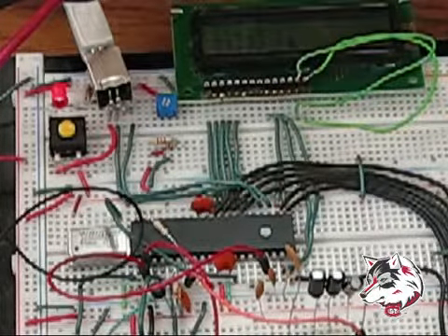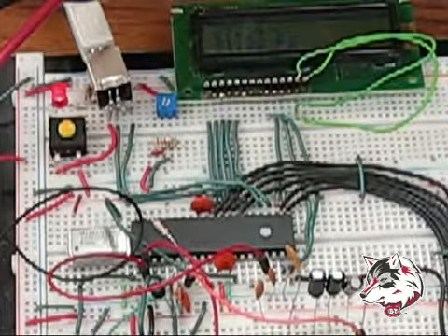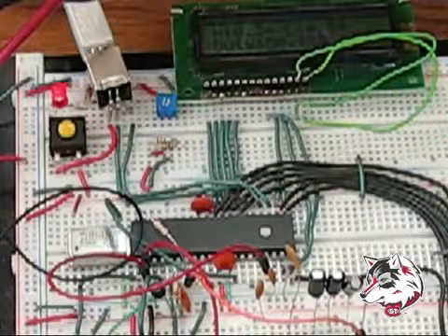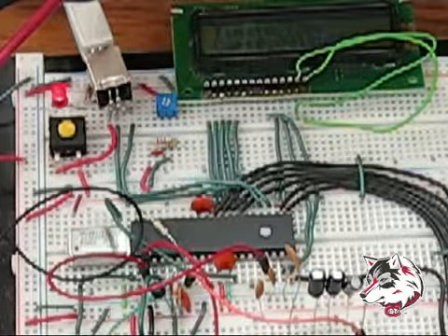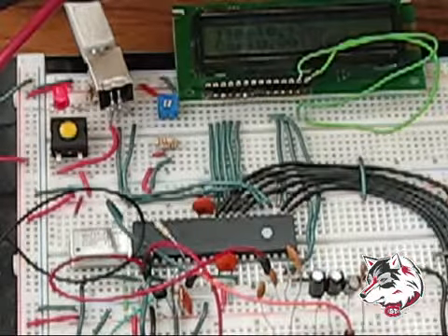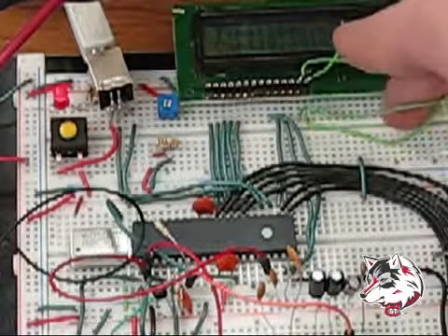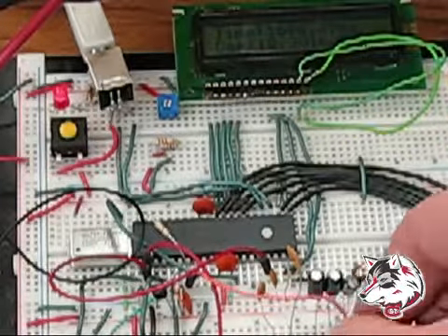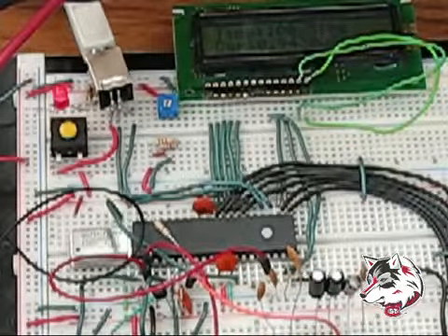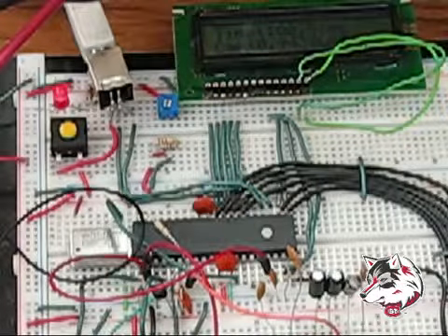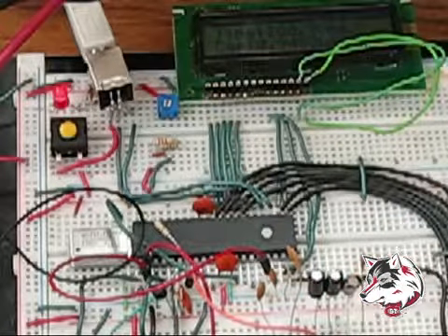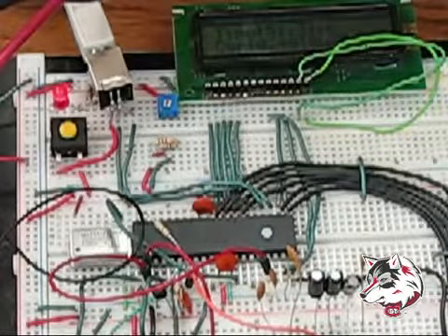If I hit 7, it's going to go ahead and measure temperature. If I hit 8, it's going to try to measure pulse width. Right now we still have the same square wave coming in here, so it's going to be 50%. And then if I hit 9, it's going to measure capacitor. So right now we're on this little 0.1, and we can move it over to the 10, hit 9 again. It's going to measure cap. Now we're on 10 microfarads. And then I believe this is a 0.47. I could be wrong. Yep, that was the 1 microfarad. This should be the 0.47. There we go, yep, measured 0.48.